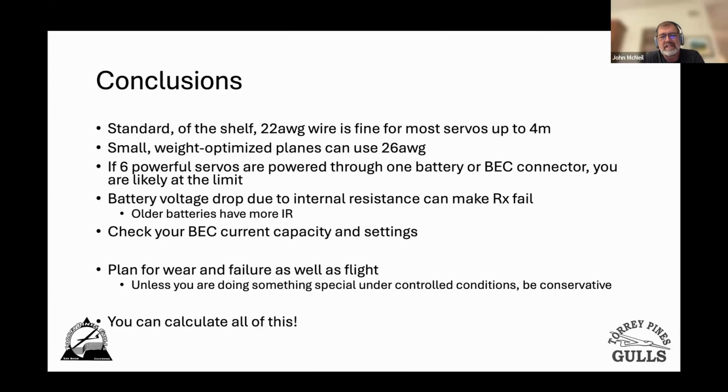The one thing I would say as an exception to what most manufacturers tell you is just fine is if you start flying big modern servos on a 3 or 4 meter plane that you intend to go fast with, even just goofing around, diving and pulling flaps, not a race plane or something, you're really pushing the edge of the connector from your battery or your regulator or whatever. So I am re-plumbing my Explorer that I had so much fun with on Saturday, and that will be getting 2 power connectors to the receiver based on the testing I did to make this presentation.